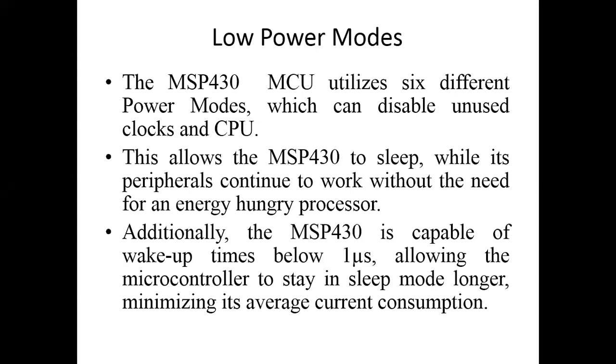Today I will discuss the low power modes of MSP430. In MSP430, there are about six power modes available. Among them, five are low power modes, and one is the actual mode, called the active mode. By using these low power modes, the power consumption of the MSP430 is drastically reduced.